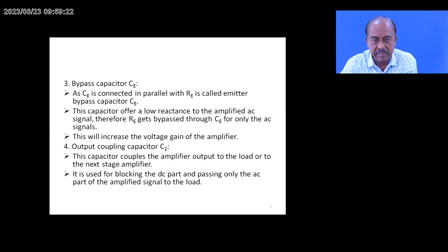Then another capacitor present in this situation is the coupling capacitor. This will couple the first stage to the second stage. In this manner, it restricts DC from one stage to another stage, or from the second to the first. It isolates the DC signals, the DC voltages, but it easily passes AC signals for amplification purposes.